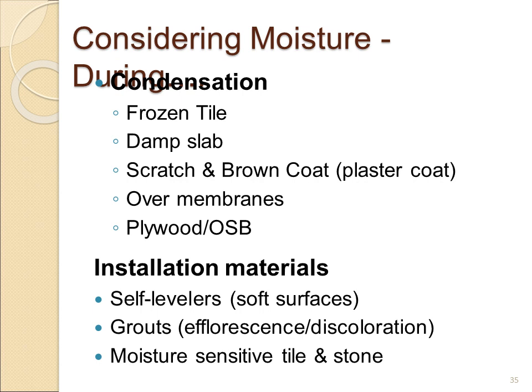Many of us are aware of green marble, where it could be moisture sensitive, but there are moisture sensitive limestones and travertines, especially if you place these materials over a deformable membrane, such as a peel and stick membrane, especially if you were to have to do some buildup of mortar underneath that tile.